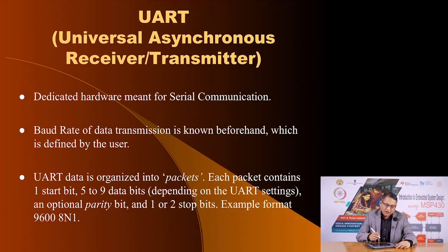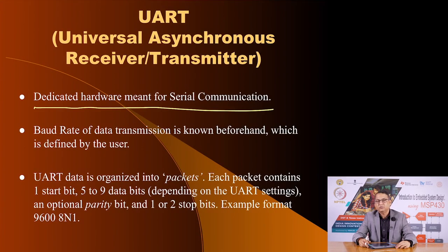UART uses dedicated hardware and it is communicating in a serial fashion. When you are transmitting data serially, you have to decide what is the duration of each bit, because we are saying the communication type is asynchronous, which means there is no accompanying clock with the data that is being sent.